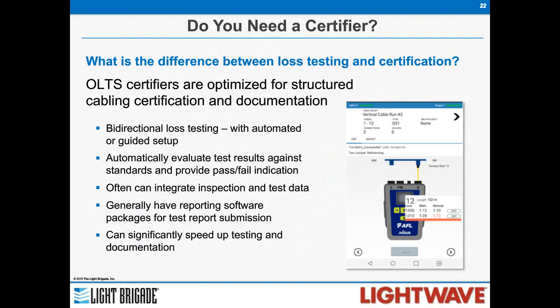So that last version, the OLTS testers that are really automated, are often known as certifiers. I'll just do one slide on this, but for anybody doing structured cabling, anybody looking to test to cover warranties, to document for warranty coverage or just for posterity, some of these certifiers can be very helpful, big time saving, but you're going to get these if you have a lot of things to test and document. They do bidirectional testing. Many of them now have automated test setups that walk you through how to reference your equipment, and with one button they'll sort of run through the whole testing scenario in both directions. So they're more costly, some of them. They're coming down as competition heats up, I think, here, but there are a lot of options out there from a lot of different vendors, and they can save you a lot of time if you're going to do a lot of testing.